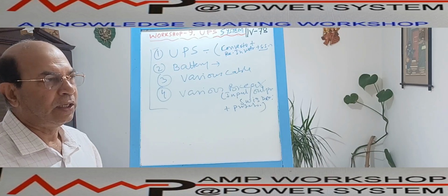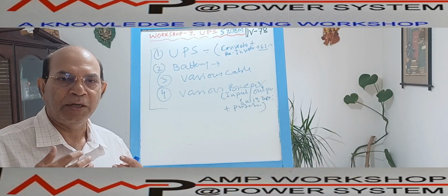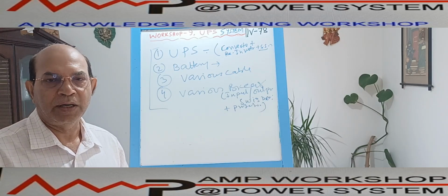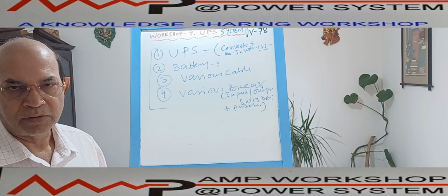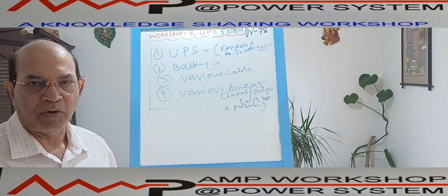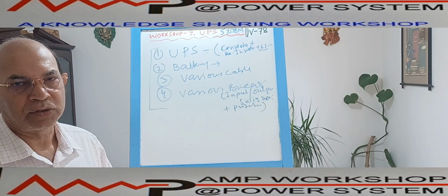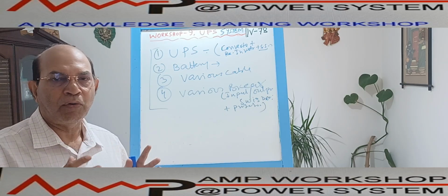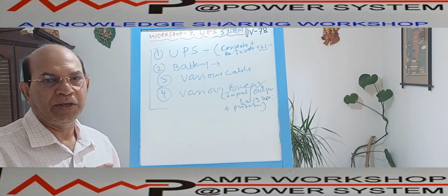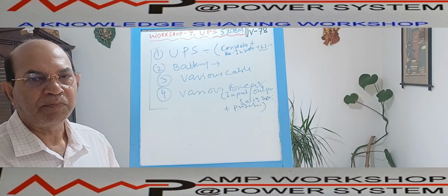In a normal electrical power system, we have an electrical generator, a mechanical engine, that may be a gas turbine, steam turbine, or hydraulic turbine, driving an alternator, and the alternator produces electrical power to the various loads. If you look into the alternator sizing, I have a video on that. These power generating devices are always sized in terms of kVA.